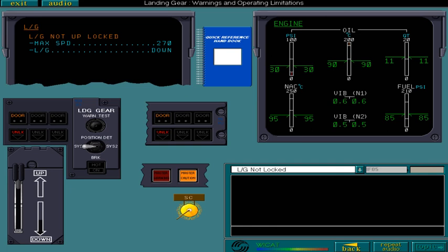Here, the landing gear indicator units show the same indications to inform you that the left main gear has not locked in the selected up position. Your only action, in this case, is to extend the landing gear. This extension may be delayed, however, to minimize fuel consumption.